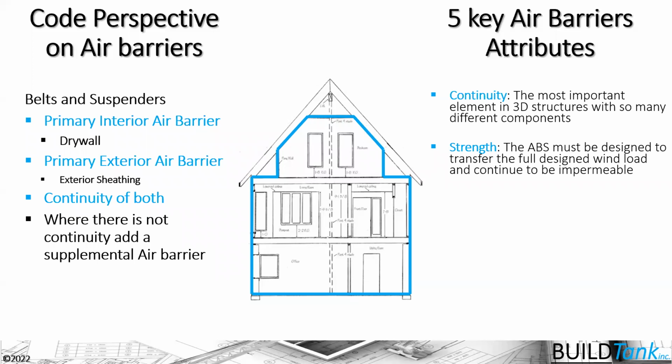Strength is a big component here. So rigid air barrier materials like OSB, drywall, foam boards, thermal plies, those work much better than flexible air barriers here. Durability is a huge issue. So placement of a correct air barrier in the correct location. Think of attic knee walls and the attic side air barrier that you need there.